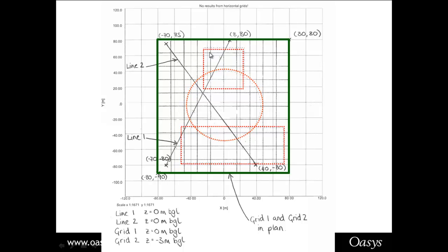And the reason I've done this is because I want displacements to be calculated within these squares. So for example, because of the number of intervals I've chosen, displacements will be calculated along these points. Now say for example I just chose 3 intervals, then the displacements might not show for inside this loaded area, and you wouldn't get a very accurate looking grid, and the contours plotted wouldn't be very representative. So it is important that you choose the right number of intervals to lie within your specific loaded area, which is what we've done here.